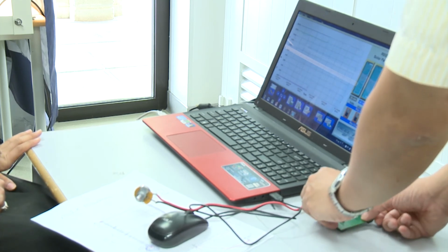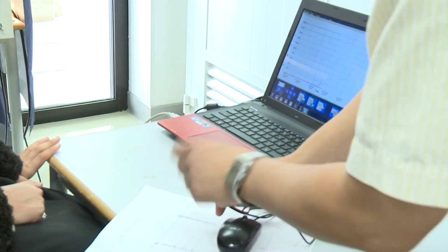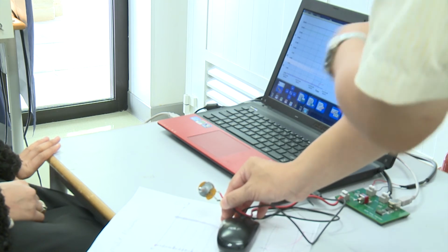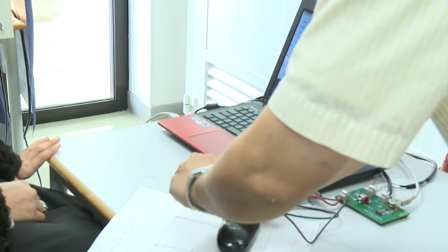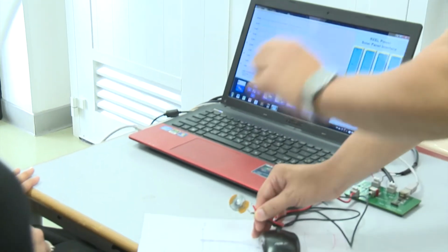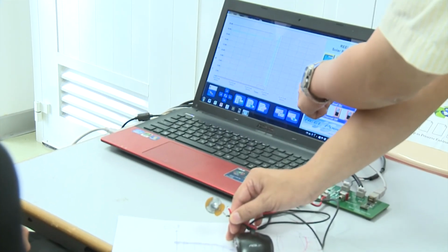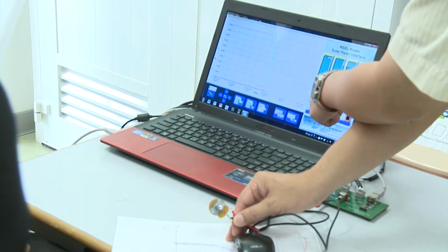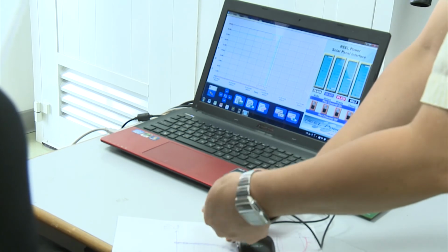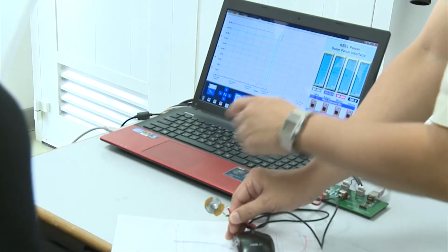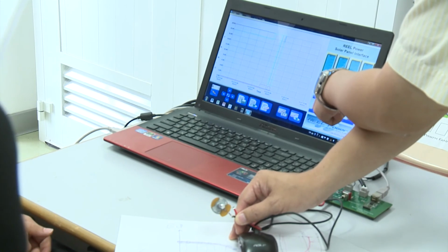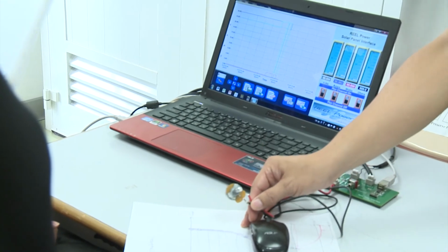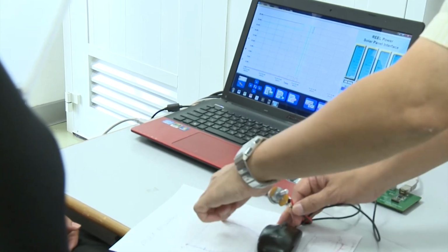Okay? Series connected, you turn counterclockwise. This is one extreme. And if you go clockwise, you go to another extreme where this voltage is 0. So it's pretty much VOC, the highest voltage is 28 something. All right? And at 28 something, the current is almost 0. Then if you go to the other extreme, the voltage is 0, and the current is 0.0363. So it's about saturation. It's the saturation current. It's this side.